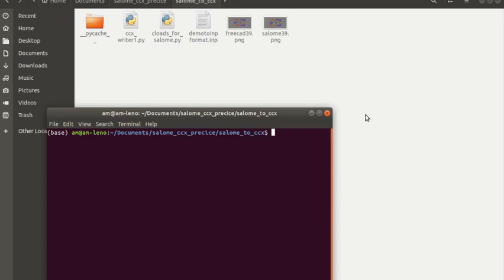But here I am using the ccx solver compiled for preCICE. preCICE is a coupling library where we can use different fluid and structural solvers together for running multiphysics simulation. So when you are using the Calculix solver, you just type ccx, that's it.